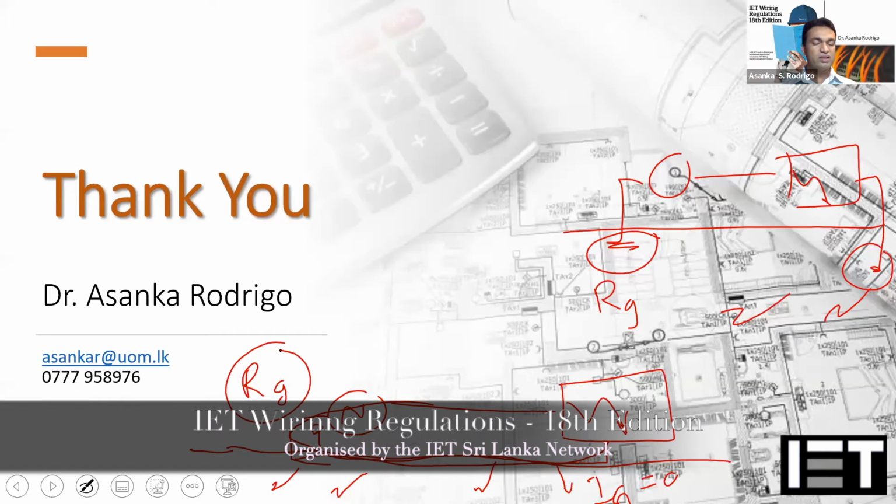Other than the lightning protection system, the lightning protection standard says that you need to maintain less than 10 ohms of earth electrode resistance value. Other than that, for the protection requirement, you are not caring about the earth electrode resistance value. Even if you don't measure the earth electrode resistance value for a TN system, for the sake of safety, other than the lightning protection, there will not be any ground current going to the grounding system. So all these aircraft, everything is designed based on this criteria. They create a closed loop, so that with the protective devices, if there is any abnormal current, those protective devices will take care. You don't want to send any current to the earth. That is the criteria in all those locations.